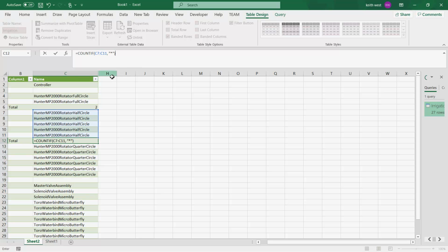That'll pick up all the text above it, so we know we've got a value of 5. Then you could copy that formula and pop it down into this area here. So can you see that it's quite easy to get that materials list out of your gCADPlus drawing?